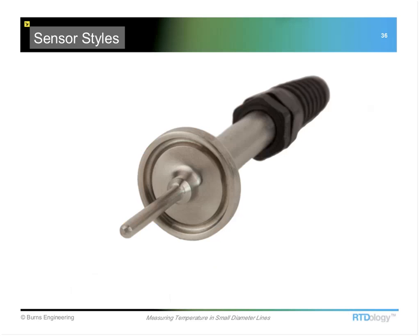This is a typical direct immersion style sanitary sensor. This particular one shows a 1/2 inch tri-clamp fitting. And this is a real common way of measuring temperature, either in a short outlet T, where we can go perpendicular to the flow, or if it can be installed in the run of a T, that's a better situation.